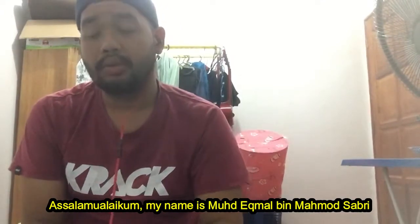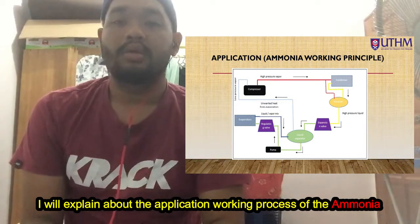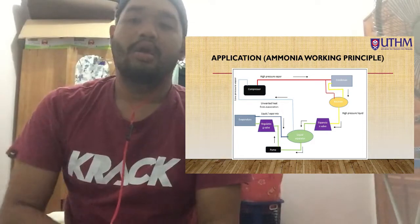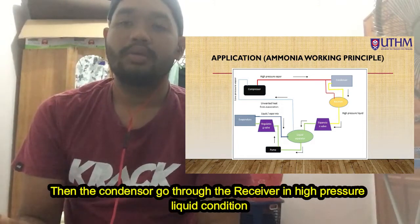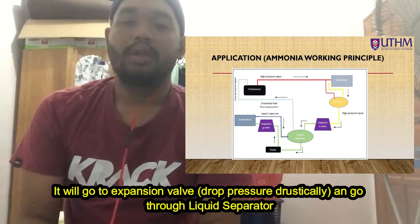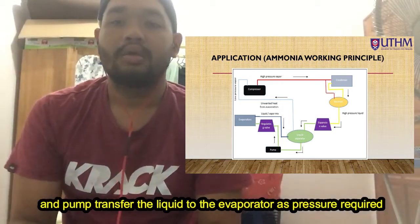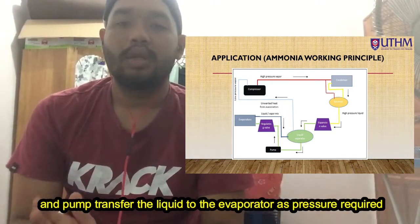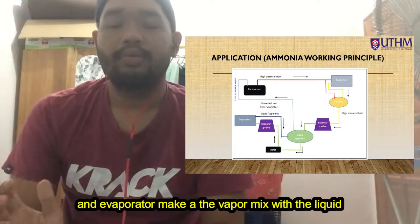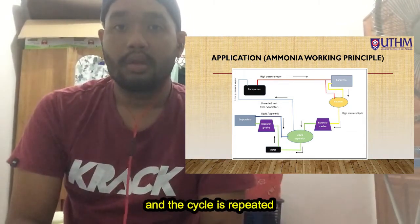Assalamualaikum warahmatullahi wabarakatuh. My name is Muhammad Iqmal. I will explain the application and working process of the ammonia system. The process starts with the compressor giving high pressure vapor to the condenser. After that, the condenser gives it to the receiver, making high pressure liquid. It then flows to the expansion valve and liquid separator, and the pump sucks the liquid to the evaporator. The evaporator makes a vapor and liquid mix, which then goes to the liquid separator, and the cycle is repeated.